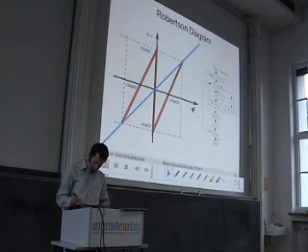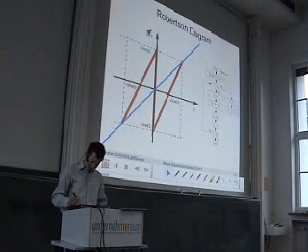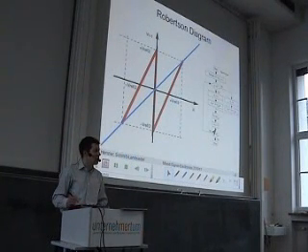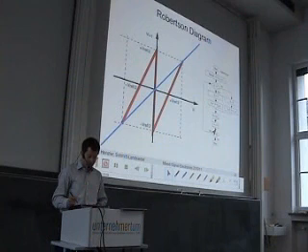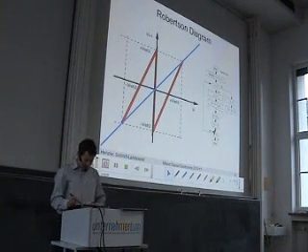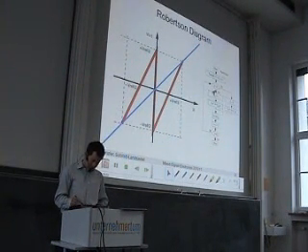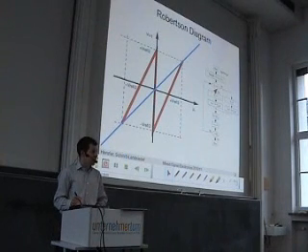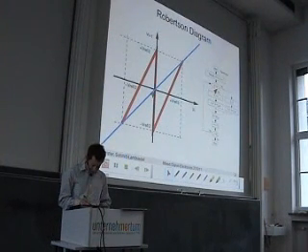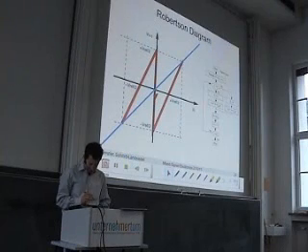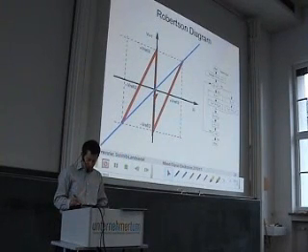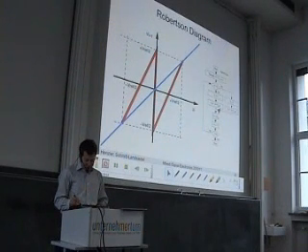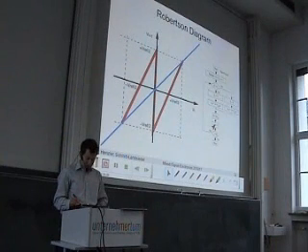So what you see here is the voltage that we use to go in here. What you see here is the voltage that we have at the output of one loop cycle. Then we say, okay, if the voltage is larger than 0, so if we are in this region here, then we compute the new voltage by subtracting Vref over 4 and doubling the result.